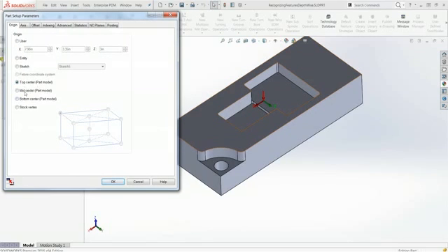We have the top center, mid center, bottom center of the part model in here, that's always been in here. Now in the stock vertex, they've also added top, mid, and bottom for the actual stock material. So if your stock's a little bit larger or a wonky shape, it'll choose the center of the stock instead of the center of the part. You can choose that in here.